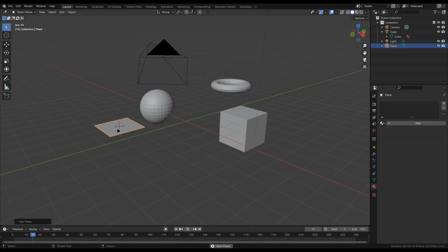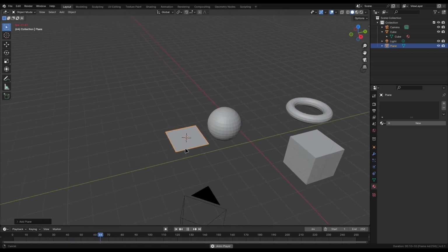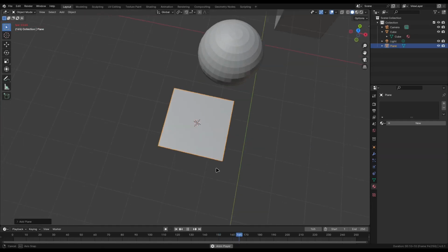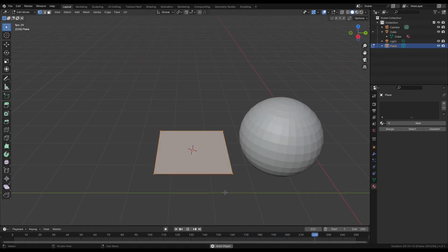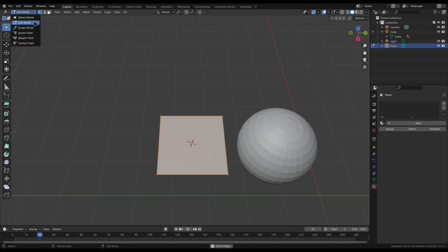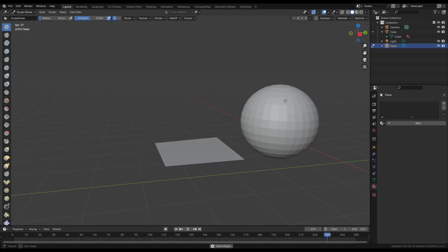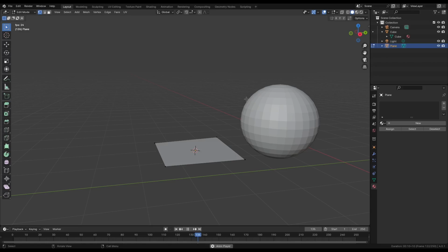In the 3D mode, there are 3 modes that we typically use for creating, editing, and manipulating meshes. We have been using object and edit mode a lot, but there is also sculpt mode. Sculpt mode is kind of like real-life sculpting. The difference is that we are still only working with vertices. We are essentially moving around multiple vertices until we get the shapes that we want. In object mode, you'll find it best for creating new objects, joining them, UV stuff, and managing the key shapes. And edit mode is used for the majority of mesh editing.